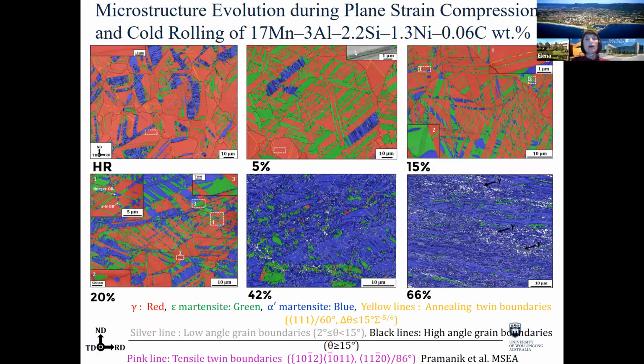If we have lower manganese steels, such as 17%, in this range, it has a stacking fault energy that is much lower, and we have only formation of martensites happening during phase transformation, no twinning.